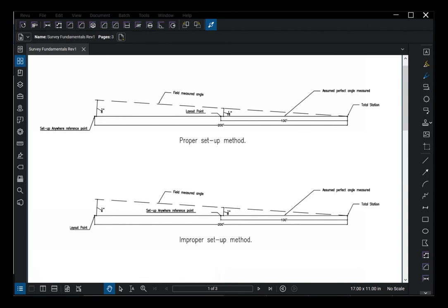During the process of measuring and storing, we must level the rod so that the bubble is precisely in the center. Field conditions often affect our ability to be precisely level when we click the Store button. For example, a wind gust, the prism rod out of calibration, or a crane load hitting the deck when I'm storing my measurement. As a hypothetical situation, as shown in the PDF, let's say I thought I was level, but truly I was out by 1/8 of an inch.